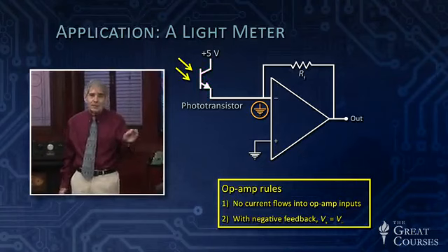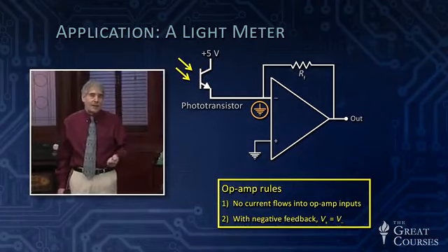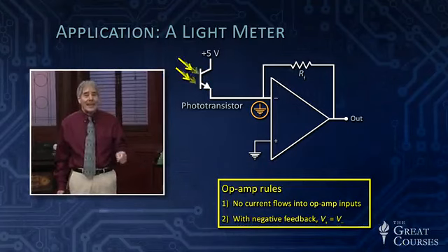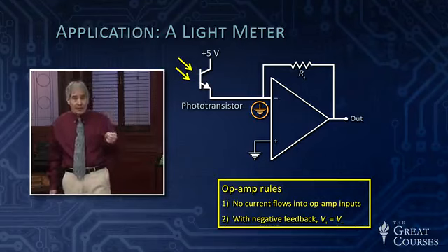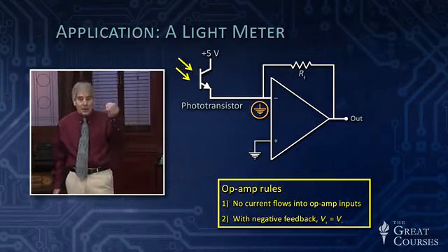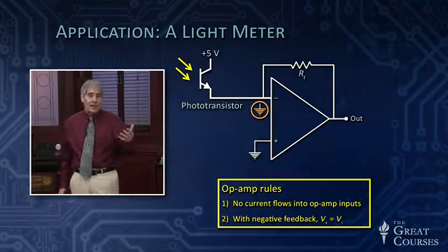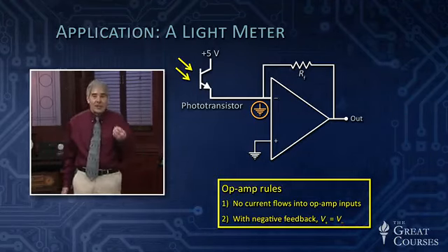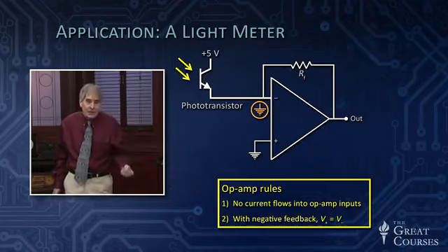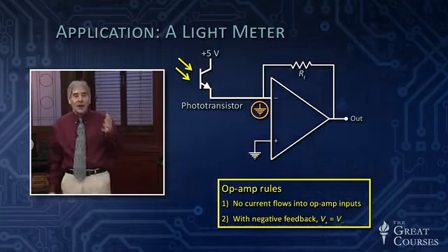And instead, it's got a couple of arrows coming in. They look like the arrows we use to talk about a light-emitting diode. They were the light going out. Well, this is light coming into the phototransistor. What a phototransistor does is it uses light to produce electron-hole pairs at the base. And when you connect a voltage to its collector, this is an NPN phototransistor, similar to the NPN transistors we've been using, you will get a current that depends not on a base current, because there's no connector to the base, but depends rather on the intensity of the light falling on that base.